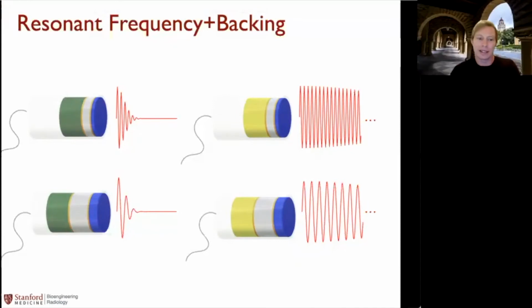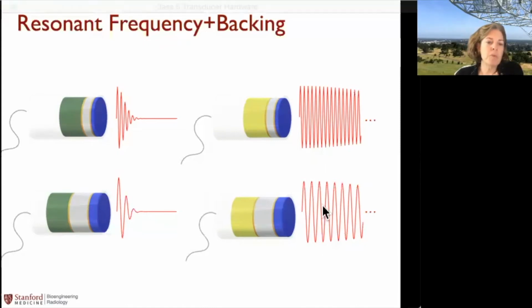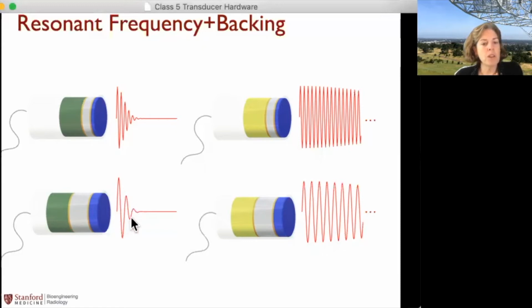So these are some of the knobs that we have to control when we're talking about ultrasound transducers. And I think, correct me if I'm wrong, Kim, but the ring down time with the low Q or that damping is really important for imaging, right? But maybe not so important for ultrasound neuromodulation. That's exactly right. For imaging, we usually want only a few cycles, maybe 3 cycles or so, because you want a really small pulse so that that gives you better resolution in your picture.